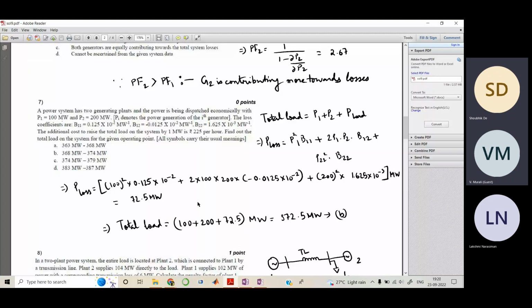Demand will be generation minus losses. Generation equals the total power in the system, right? So that would also incorporate the loss, right? That is why your generation is always slightly more than the demand, to incorporate those losses. Okay, right? I hope you got it. Because you have a big transmission line network, when you flow current through that, there would be losses. So that is why demand is fixed, and you have to somehow vary your generation to meet the demand, right?